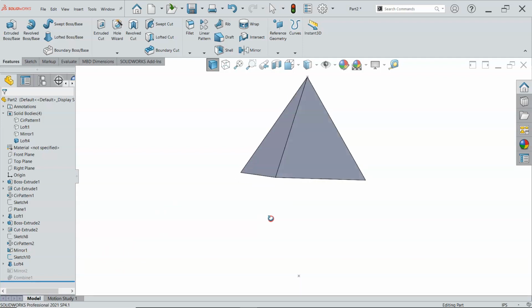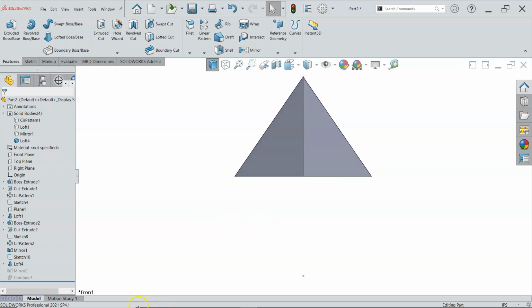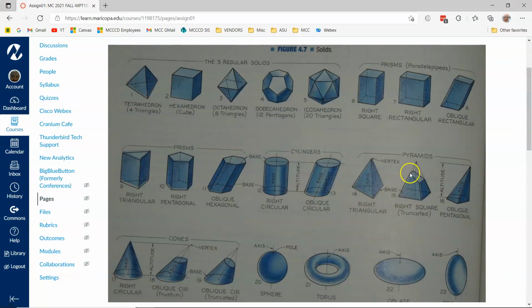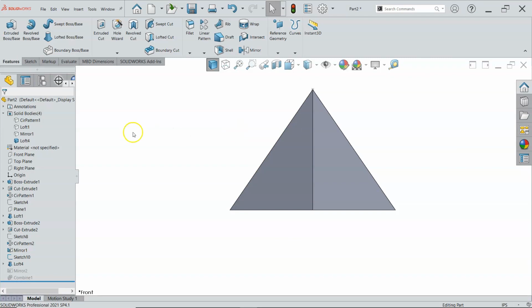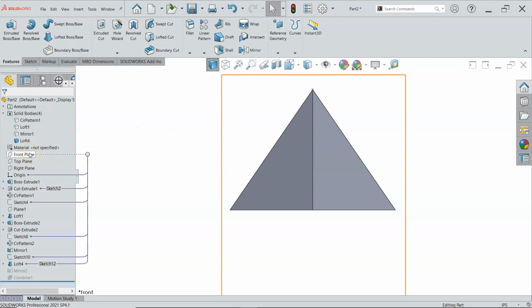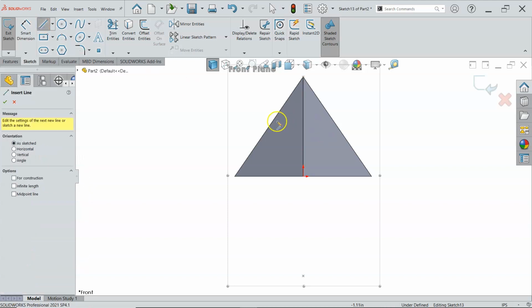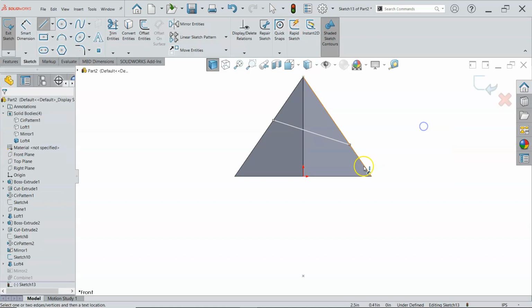And because I've rotated this over, I've got some interesting things going on when we look at the truncated geometry on the right square, it's kind of going across one of those faces. So since I've made that adjustment, let's just do some experimenting on which way these planes would go. If I go to the front plane and open a sketch, and I just pick an angle, I'm just going to do the extrude cut.